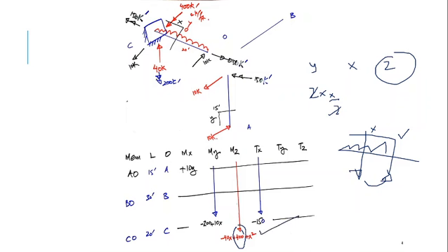And finally I have this 40 kip, this is in y, this member is in x, y, x gives you z. Moving this 40 kip towards this point gives you plus 40x in z. It has to be balanced with minus 40 because it is forming a clockwise. So I have applied a minus 40x. In this way, all the entities in this moment table have been identified.